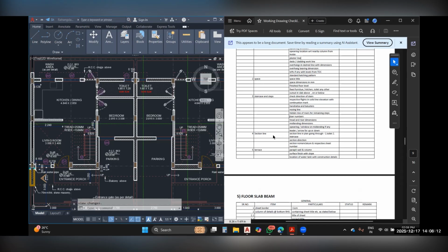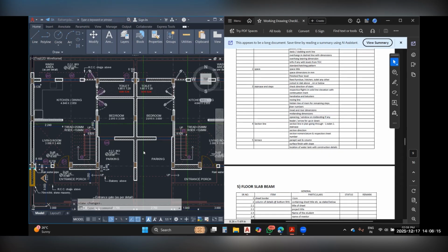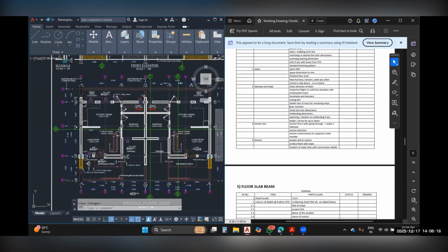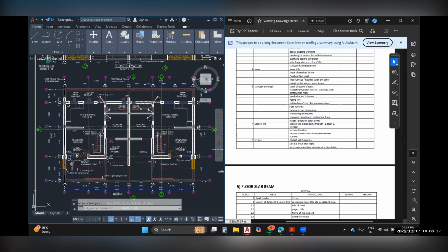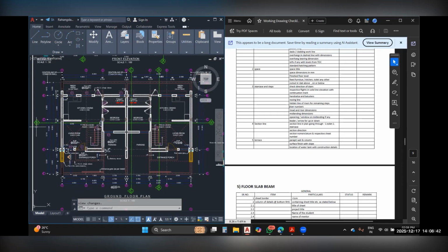Now moving towards the next section, that is showing the section lines. As I said, you need to constantly coordinate the plans along with the section and elevation. In the plan, you need to show the section lines. Now these green lines are representing the sectional plane and the direction into which the section has to be interpreted. So this is section BB dash going through the living room and through the bedroom, looking towards the kitchen.